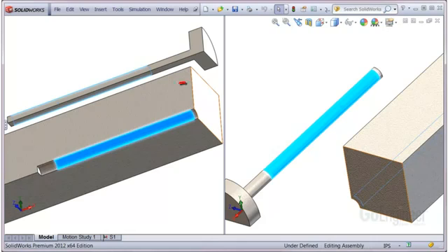Notice that I excluded a very short length near the head of the bolt and away from the end of the bolt. This is because you will see very high stresses directly at the edges caused by the rapid change in geometry, which would be unrealistic in an actual structure.